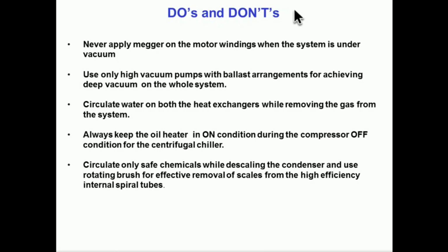Whenever you have to remove the gas from the system, especially water-cooled systems, you need to circulate the water. If you do not circulate the water, there is a chance of the tubes getting frozen. Whenever we remove the gas, low pressure is created, and low pressure is directly proportional to low temperature, so it can freeze the water in the tubes. So try to avoid this: circulate the water and then remove the gas.